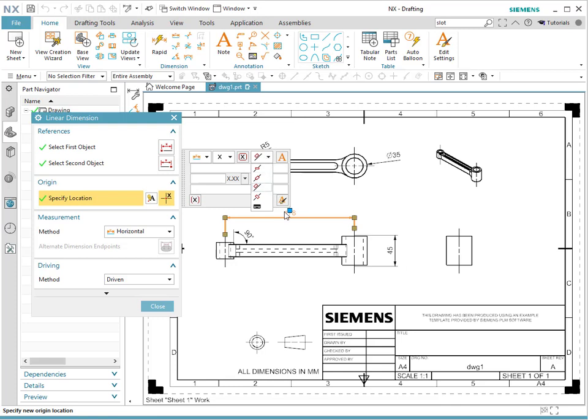Notice that in this case it's horizontal because the dimension that you have is horizontal. However, you could change the position where it goes. In this case it's on top of the line. You could have it go in the middle of the line, in between, above, or completely perpendicular to the line. So for example, if we change something, notice that the number goes in between the line now.